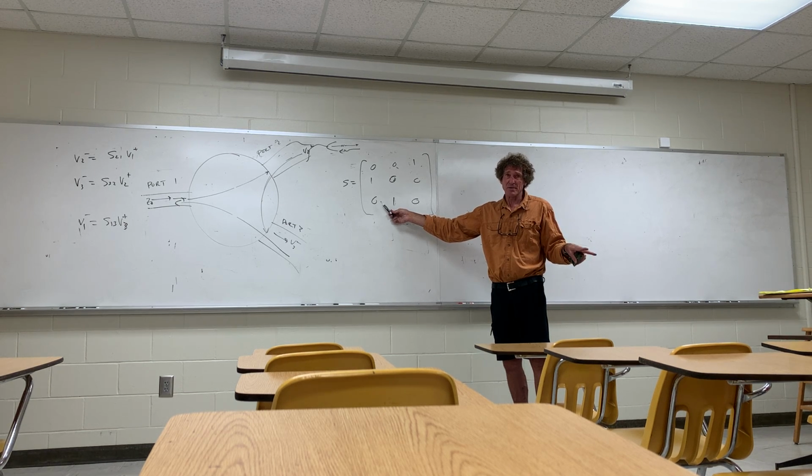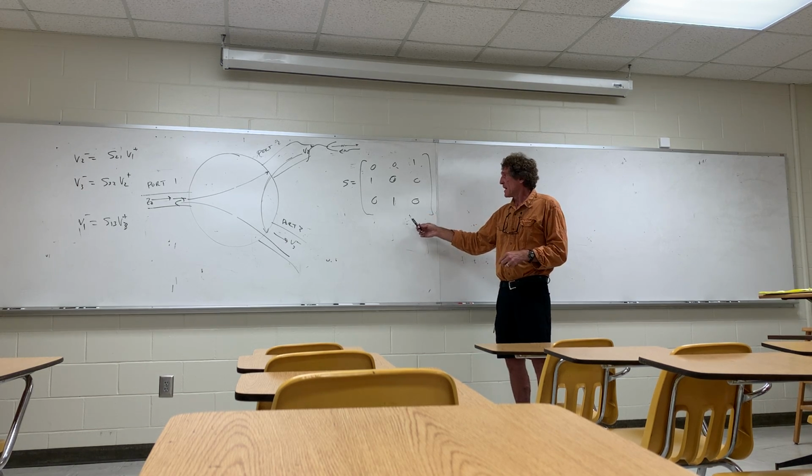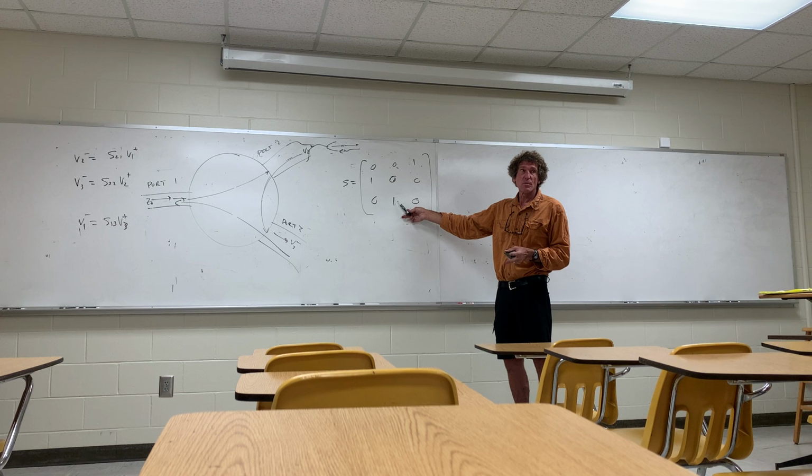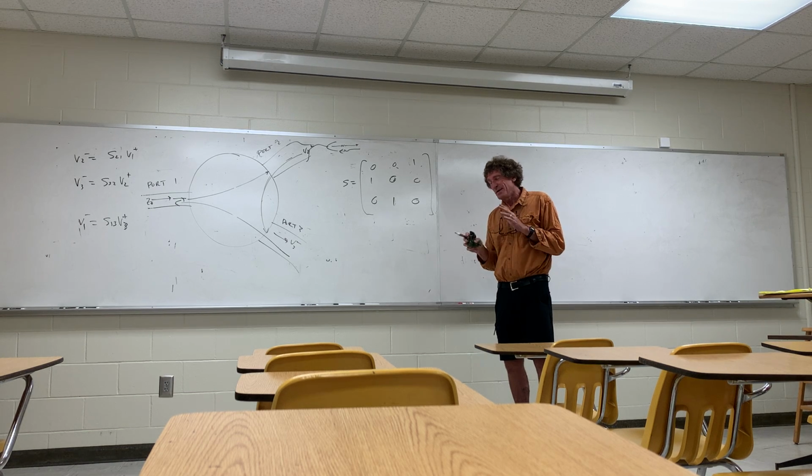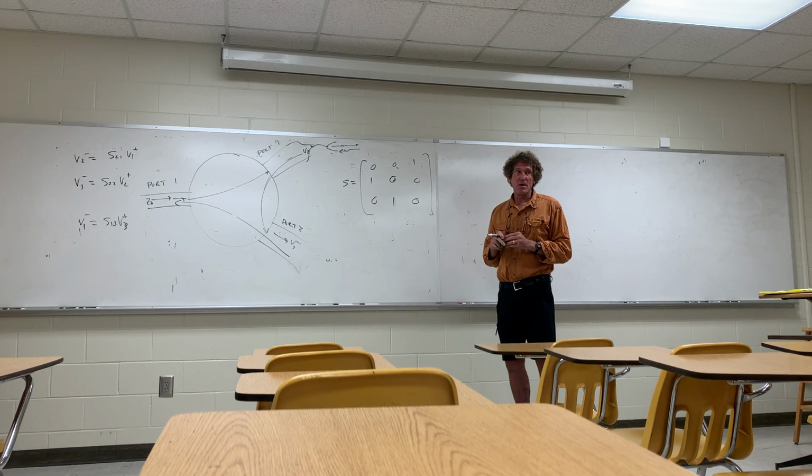Well, it won't be that. You might have minus 40 dB, minus 30 dB. It won't be minus infinity. And when we talk about a forward voltage gain of 1, you won't get exactly 1. The log of 1 is 0, right? You'd have 0 dB of loss. That won't really happen. You'll get something close.